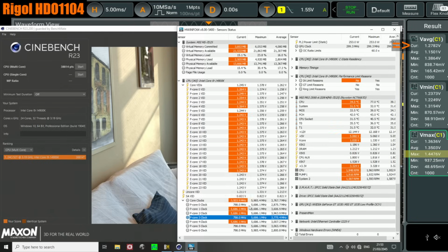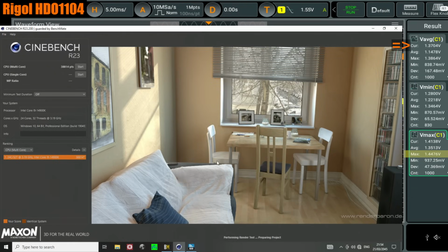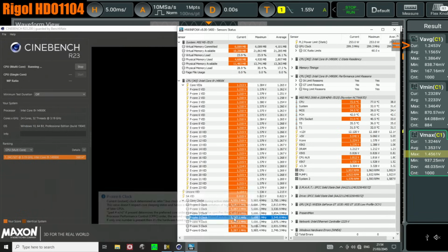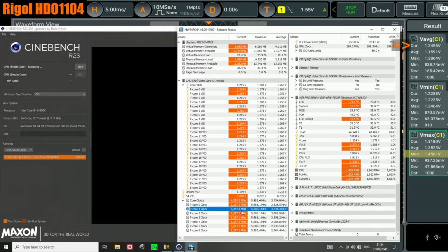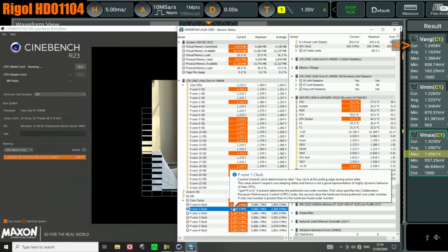With the Intel default settings, this CPU usually runs like 5.1 gigahertz for Cinebench. Now that we've offset the voltage by 70 millivolts, instead of running at 5.1 gigahertz, it runs at 5.2, and the VID actually runs at like 5.3. And the VID voltage for this higher frequency is higher, right?